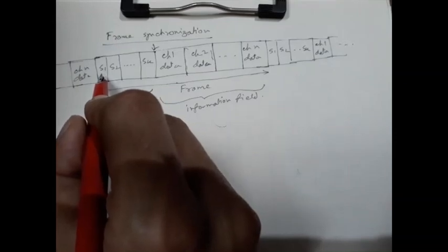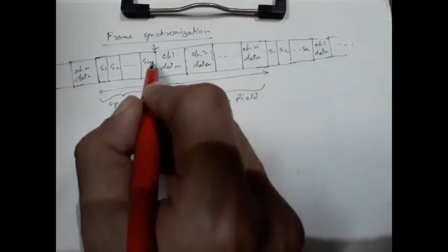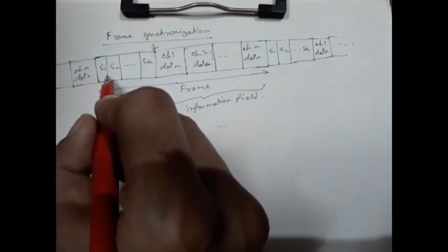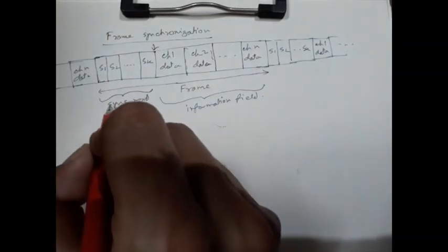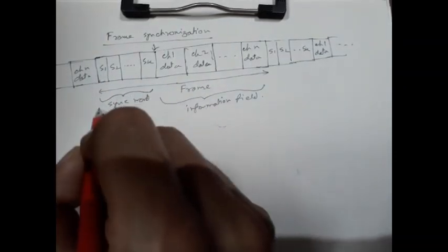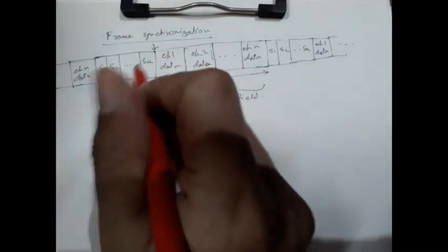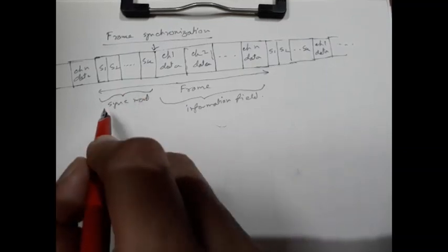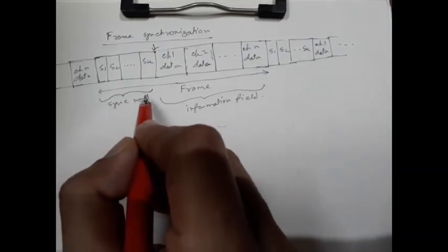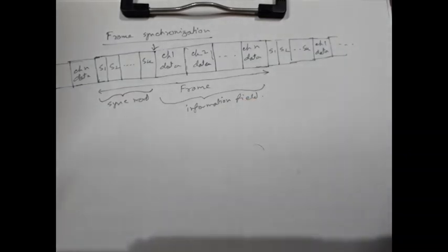And it must not be very small either, because a tiny sync word may match with the channel data. So the choice of sync word is very important for this particular situation.